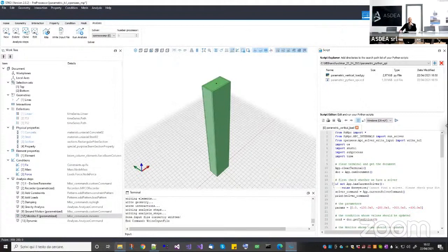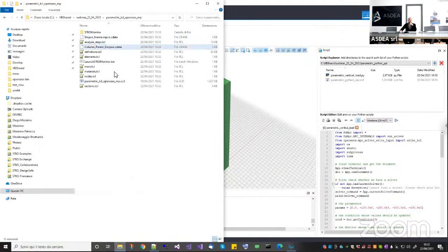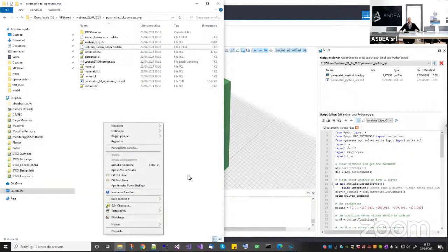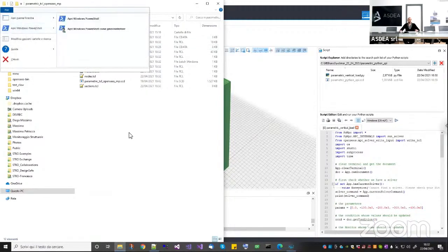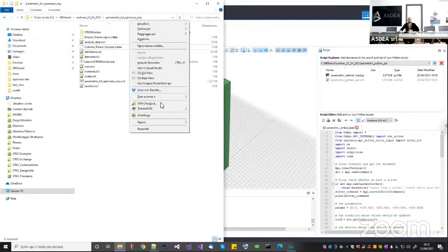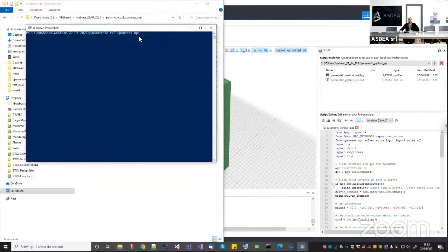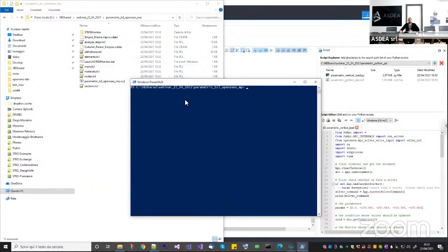You write the input file, you are here. Once your input files are written, you can simply open a command shell, okay? So if you don't know how to do it, you can just click on Shift and right click, or you can go in File here and open a command shell, okay? So open a command shell in this folder, which is the folder where you produced your STKO file. Then you need to type the command for OpenSeesMP. In my case, I have it here, OpenSees solvers, OpenSeesMP.